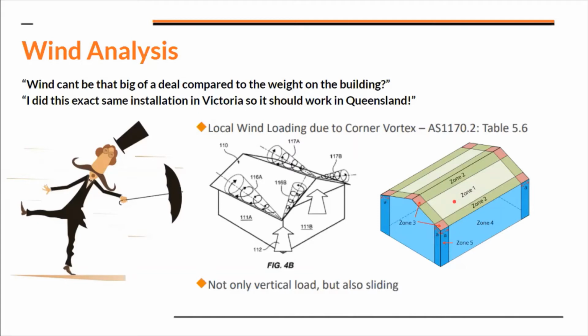But because we don't have even a basic understanding of how this wind pressure works, sometimes we find that the panels are initially proposed in the wrong spot. On the other end, if you're filling up the entire roof, understand that zone 1 may be okay, zone 2 is probably going to be critical but probably okay, but the corner zones, maybe I shouldn't put panels there. Maybe I shouldn't tell my clients we can have these extra, combined maybe 30 panels, 10 in each spot or 5 in each spot, right?